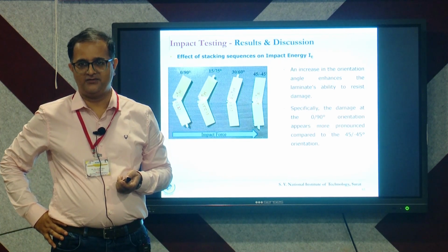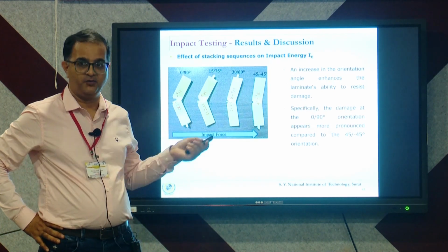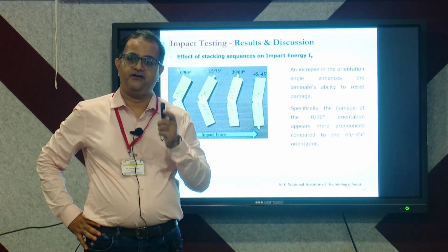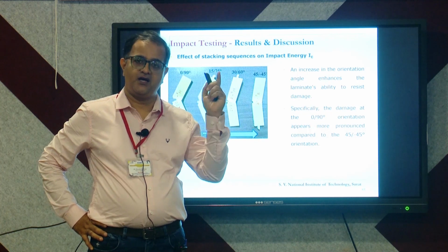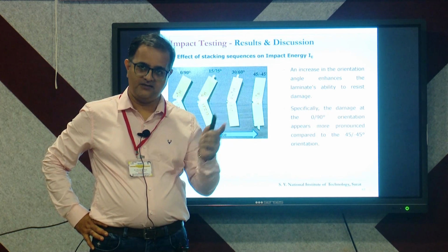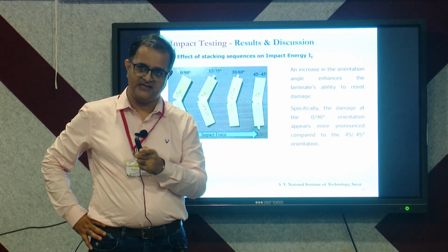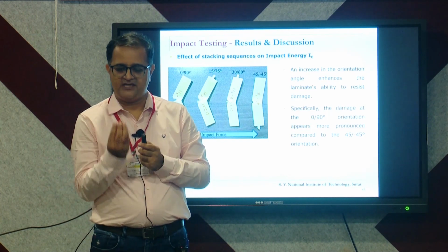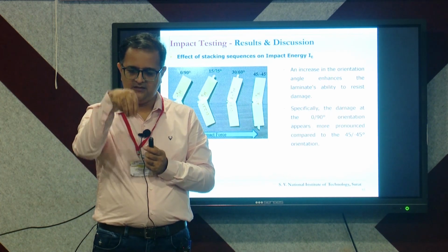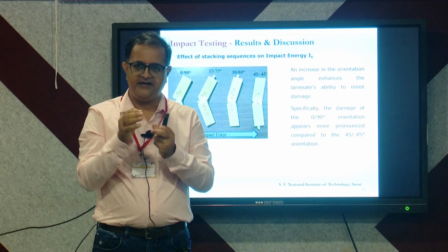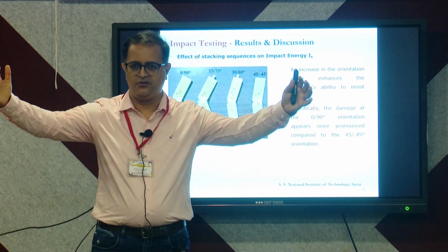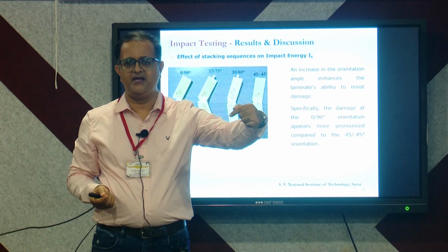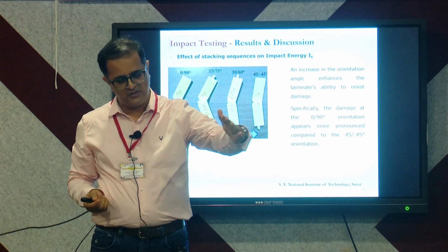Yes. Permeability was a different study, and I haven't included it over here. But yes, in fact, the way you are deciding the flow of the resin will also have its effect. Permeability would change when you fill the resin from the center and allow it to percolate along the radius, or you allow it to come through a diagonal corner and then flow.